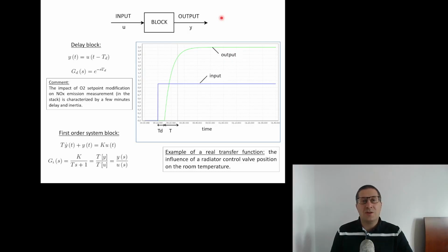First of all, I would like to mention the fact that processes in industry are characterized by some dynamics. Usually it's a transport delay and first or second order inertia. So it means if I change the input, my control signal, my device load, I open the valve, I push more air, I change the flow of the water, I will not see the instant reaction of the process outputs.